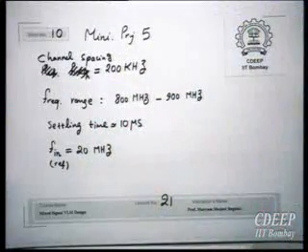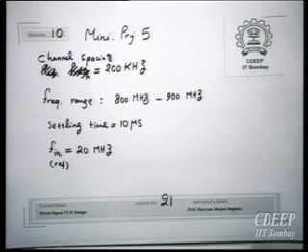You have a counter, and the settling time should be 10 microseconds. Therefore, there is enough freedom. There is no limitation even on the current of the charge pump, because here there is no limitation on the power. Of course, don't make it several amperes, that is too big, but it's okay. It's not limited in the current.